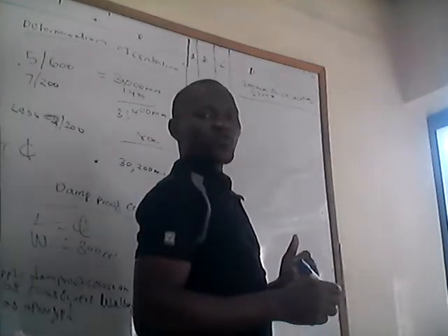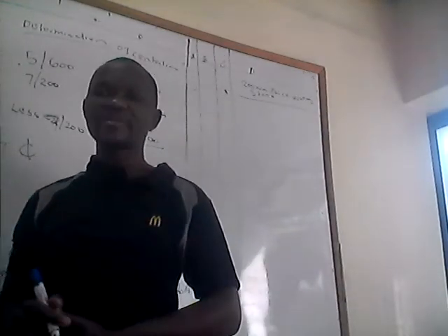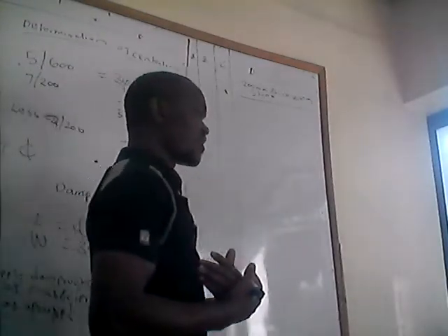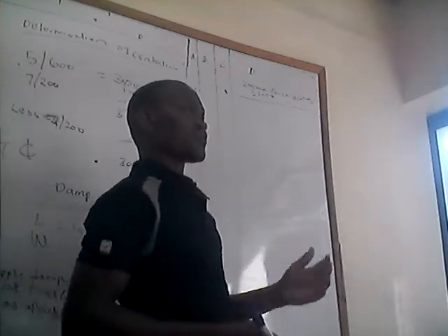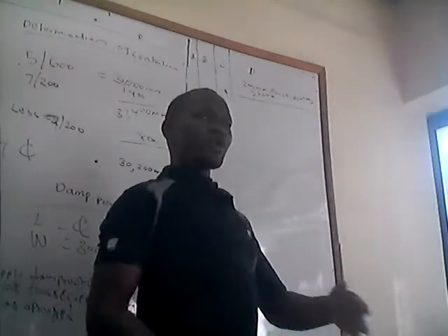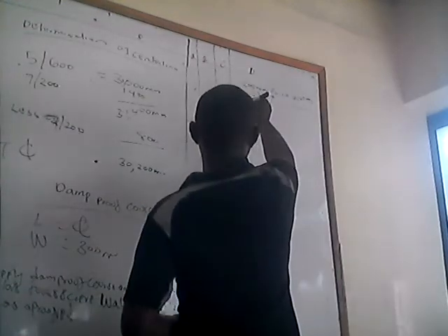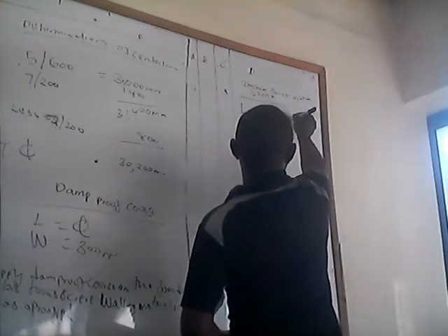According to standard methods of measurement, walling is measured in square meters, the superficial method. It means you have to open the wall, so for the length, we open all the wall, where we had already gotten the center line, which is 30,200 millimeters.